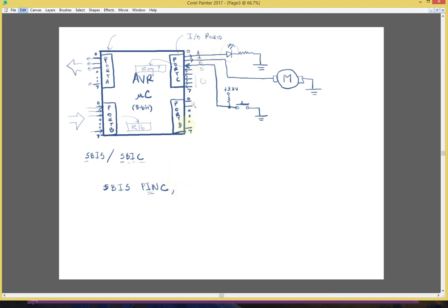Bit 0, 1, 2. Okay, so that means when this is pushed, this test will pass. So therefore the next instruction will not be skipped, and that might be a procedure to say turn LED on. Or alternatively, since we can do that particular task with one line of code, maybe I can just say SBI port C bit 0.